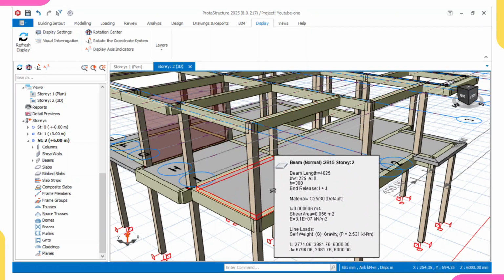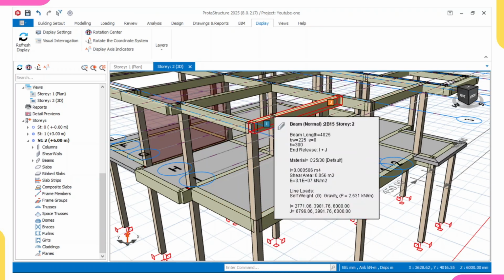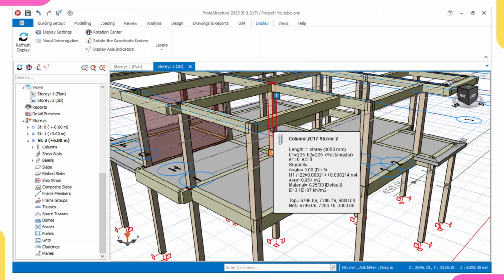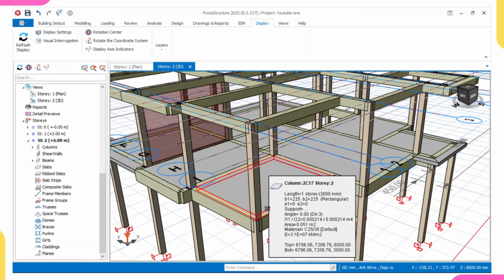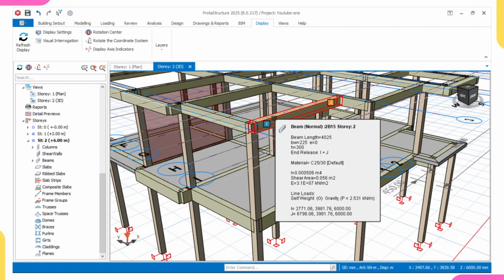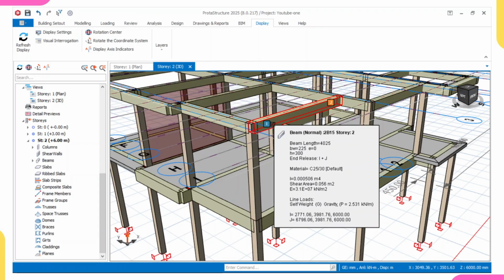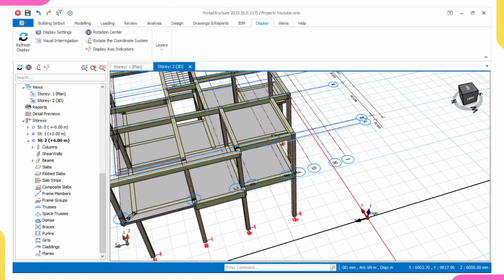So in our wall load, that is the height of this story from this slab to this top here, minus this beam depth, which is 300. If you do 3,000 minus 300, we'll be having 2,700. So that's how I got this 2,700 that I use for my wall load height.